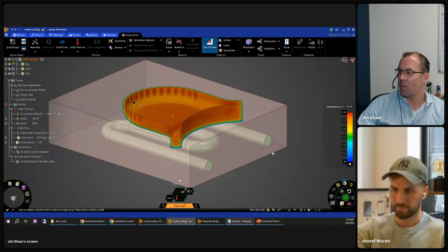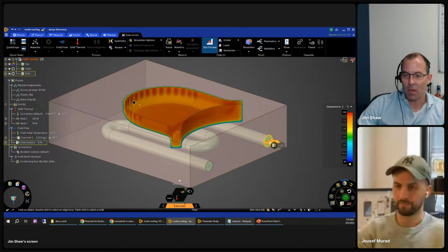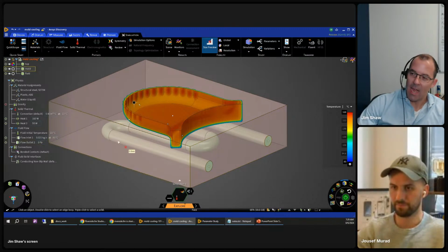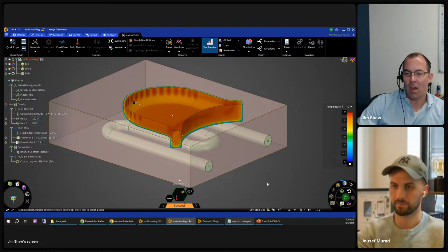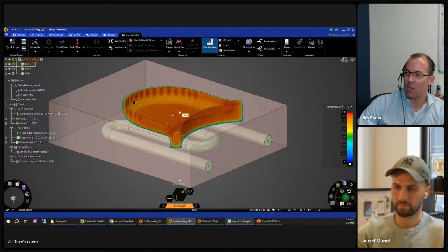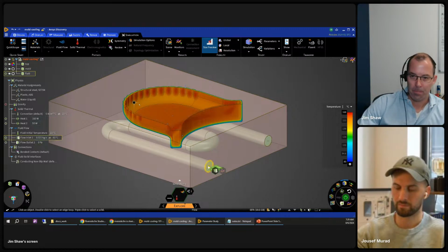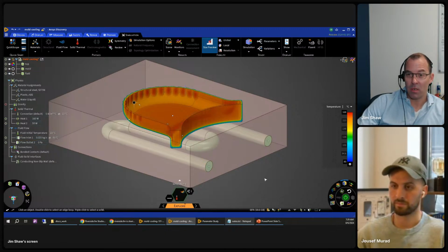Okay, what's the average exit temperature here? Yeah, we get that within a degree, right? What's the exact heat transfer coefficient on this bend versus that bend? Maybe we're a few percent off here and there, right? But the level of engineering of digging into the exact local heat transfer coefficient is rarely done. What do we care about? What's the average temperature in here? Throw 2 thermocouples on. What's the outlet temperature here? Throw a thermocouple on. What's the flow rate? When I go to match the test data, I'm only putting 2 or 3 sensors on here, the most important ones. So forced convection, conjugate heat transfer without radiation, all good.